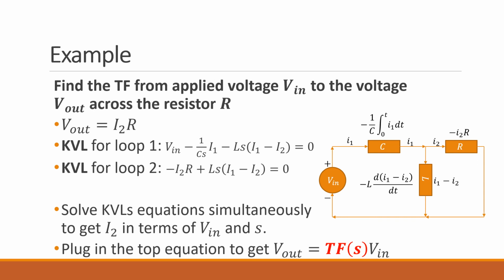Finally, note one thing. We always end up taking Laplace. So why don't we just skip a step and just take Laplace of the resistor, capacitor, and inductor relationships. We'll get V equal to I times R for resistor, V equal to I times 1 divided by Cs for capacitor, and V equal to I times Ls for inductor.